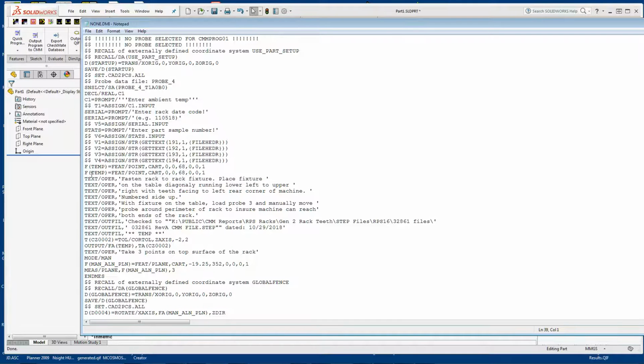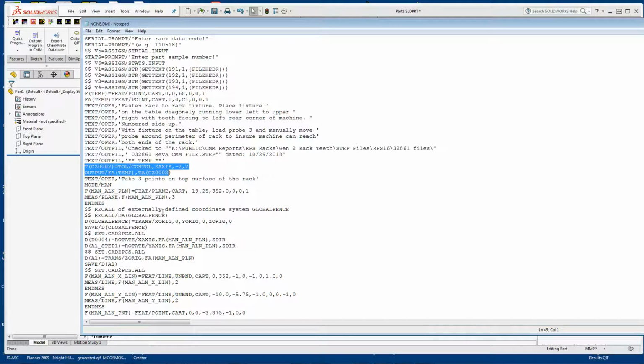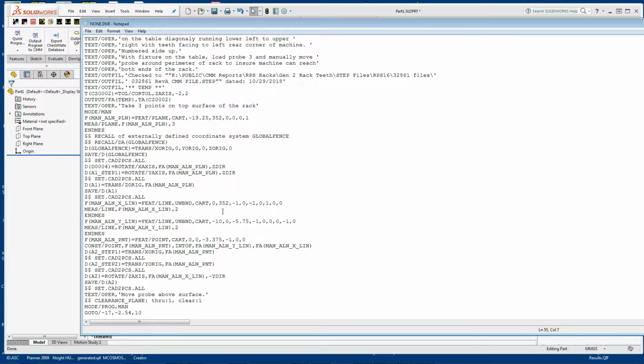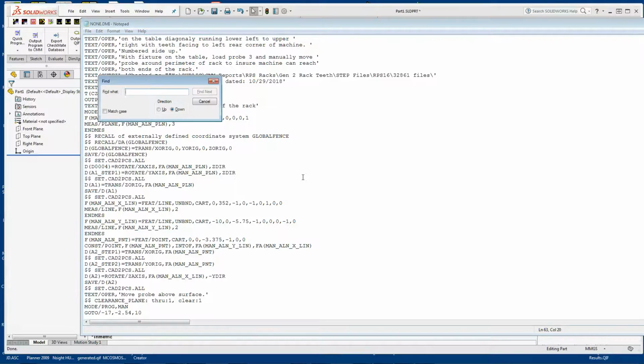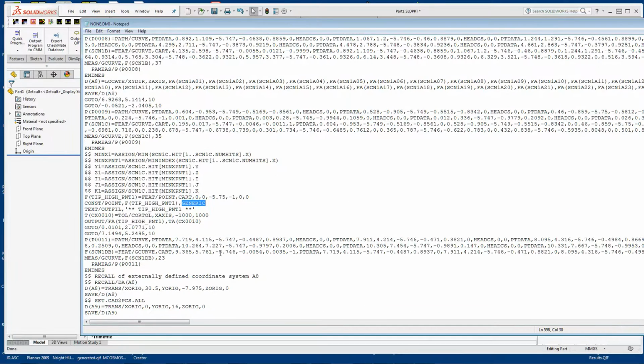But the easiest way to do this in DMIS is just to have an FA being defined, and instead of the temperature being nominal, we use that variable C1 to set it. So now we have a nominal of 68, and our temperature is plus or minus 2 with respect to that. And so we're outputting this temperature tolerance here, which is an interesting way to get a temperature into a coordinate tolerance. So if I search for that generic, the next case looks like this.